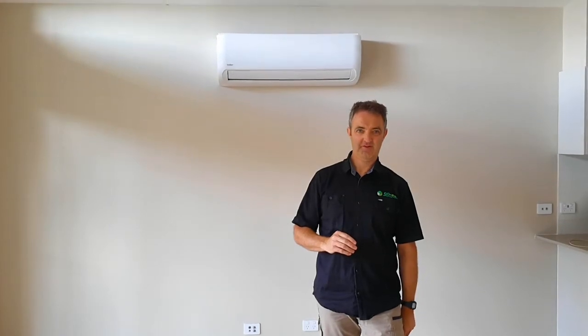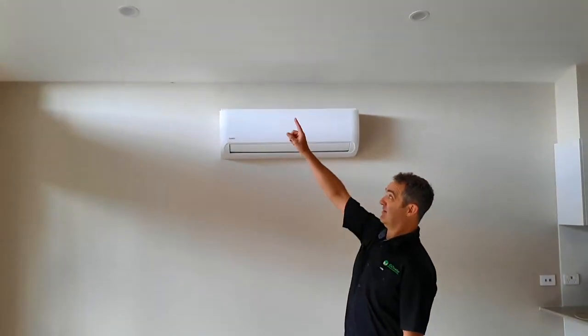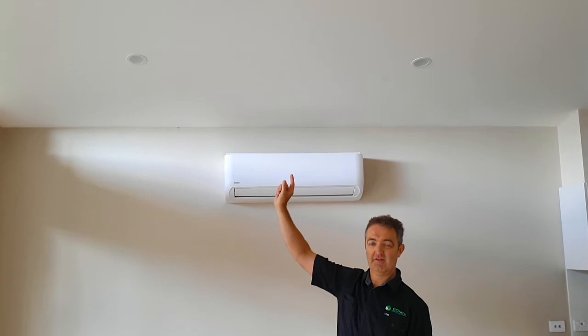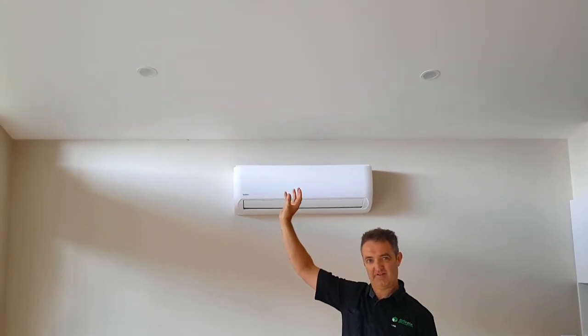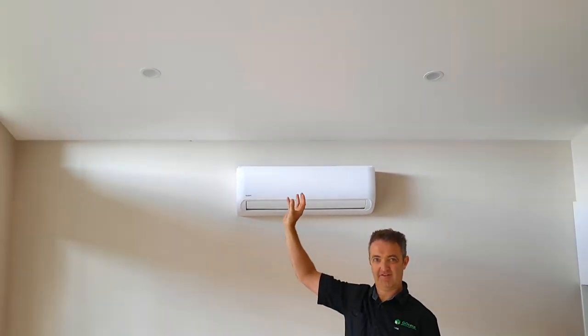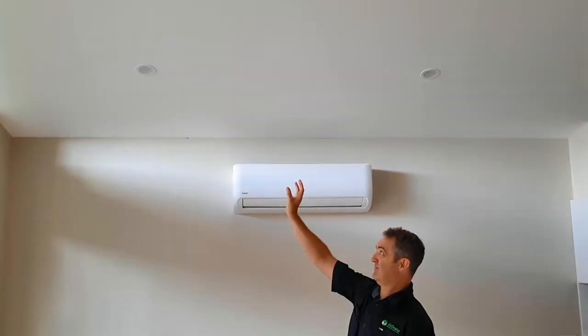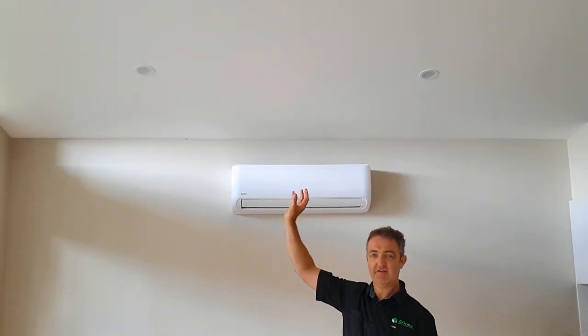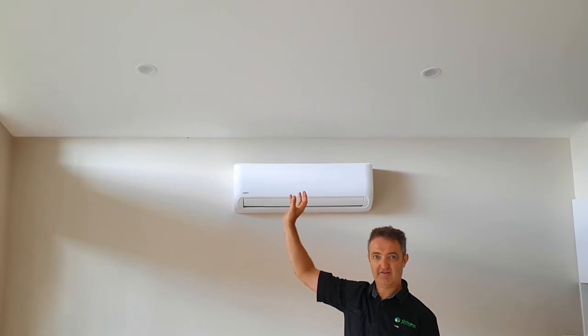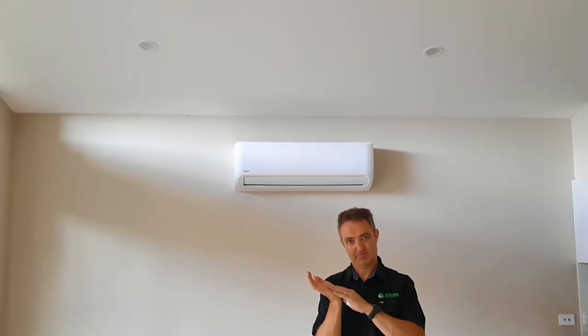Here are two more potential leakage points. Recessed downlights in ceilings. The older style recessed downlights are shockers for air leakage. These newer ones are actually a little bit better. They're IC rated, IC standing for insulation contact. What that means is the insulation is allowed to go over the top of the downlight, so you don't have any gap in the insulation. Also, the IC rated downlights have a gasket to the ceiling, so they actually seal pretty well.